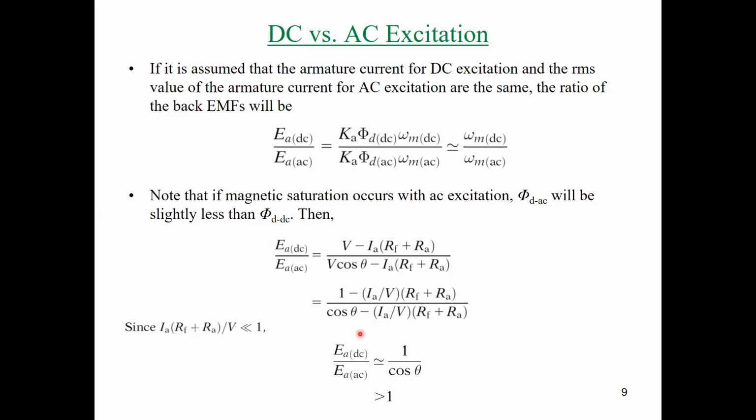Last example. We said if we have a certain impedance, I will write it down here. You have an impedance like that, and you supply this impedance by a DC source, and you have here R and XL. So in case of DC, what will be the value of current? IDC is equal to VDC divided by R.